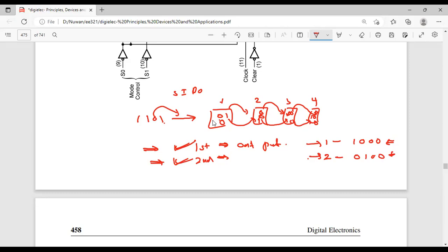This shift register can be very easily constructed using XOR. The implementation is not very hard. In most actual circuits, this kind of shift register is made from XOR and flip-flops.